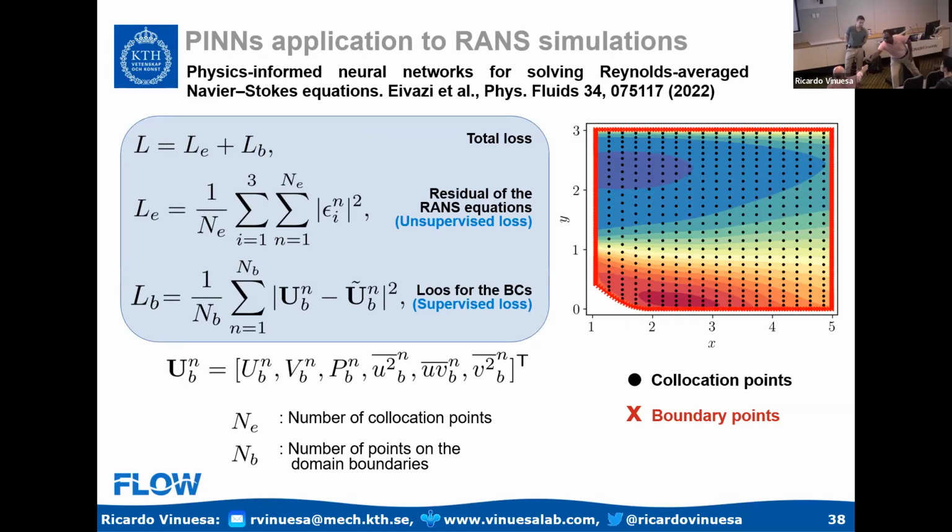Yep, Julio. Thank you, Ricardo, for this very extensive talk. In this particular case of the Reynolds-averaged Navier-Stokes equations, when you go back to your neural network, you've got data. Is that data time dependent, or is it just a steady, statistical data? It's the statistics from the DNS. Okay, so the statistics from the DNS is the input to the network. Correct. Now, is that at the boundaries? Only at the boundaries. Nowhere else. We just give boundaries.